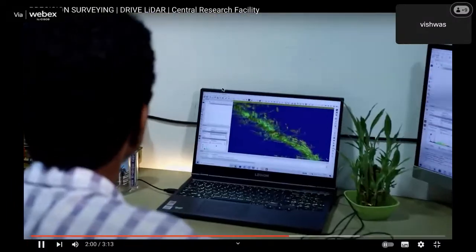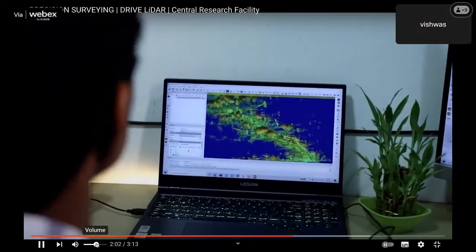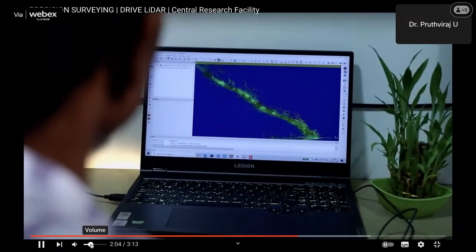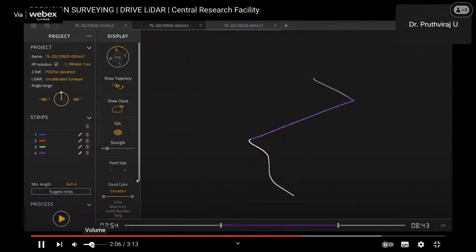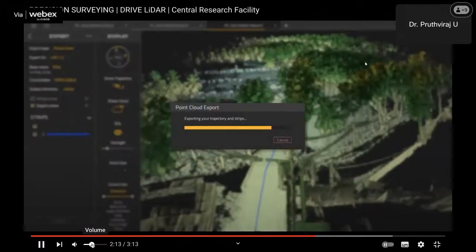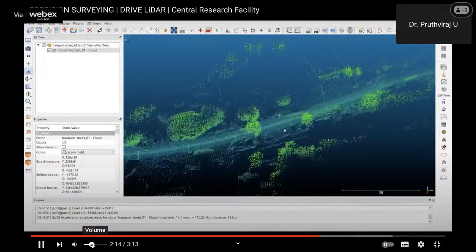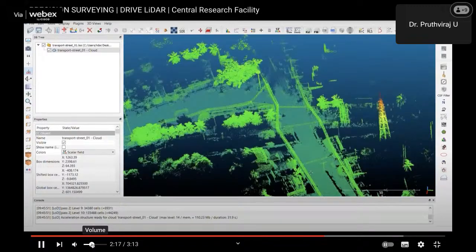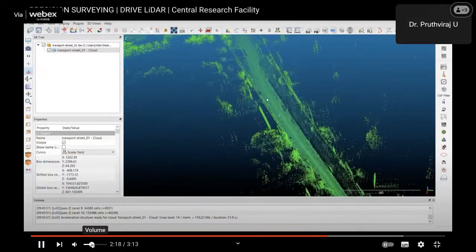Georeferencing software and point cloud registration are then used to post-process the scanned data. The output of the survey is a highly precise 3D map of the NITK campus, which is showcased here. The processed point cloud can be exported to LAS, laser format for general applications.